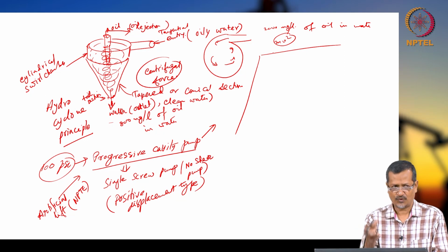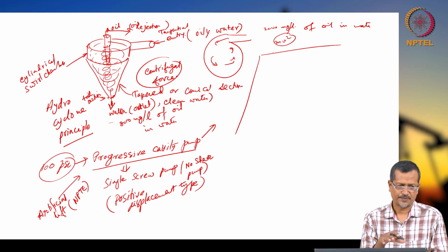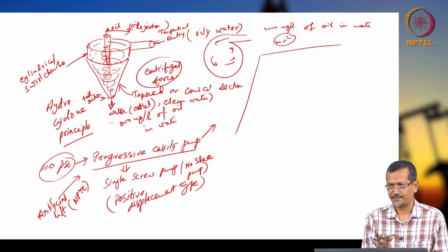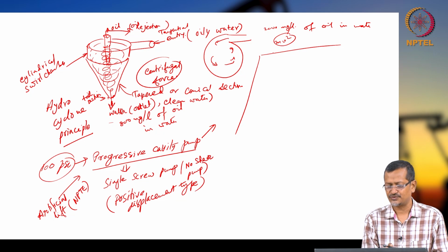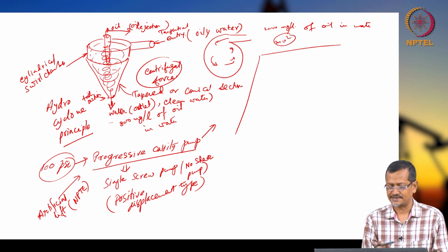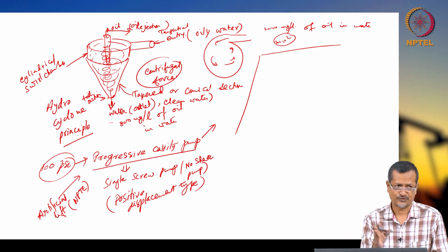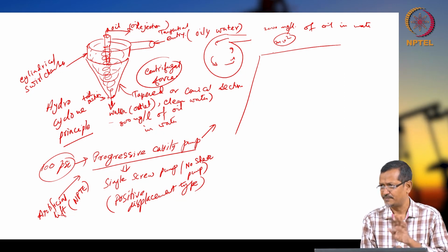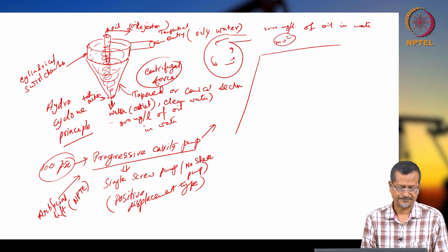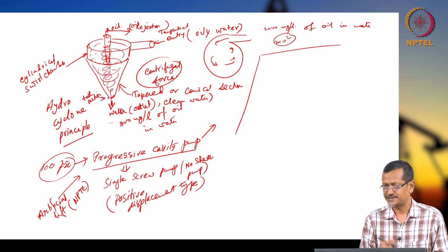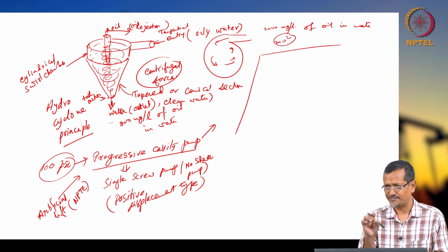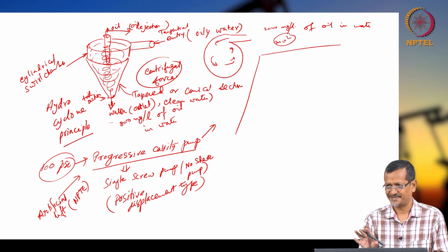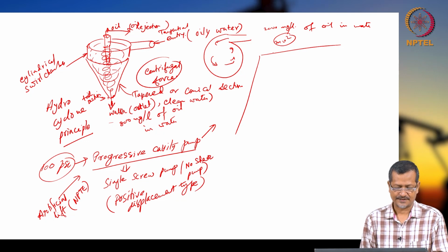If you have lower pressure than 100 psi, then most probably you will require one pump. Again, any pump you should not use, rather you should use a non-shearing pump. One example is progressive cavity pump or single screw pump. Multiple screw pumps they can also use, but they have given the example PCP, so just remember that. And the basic disadvantage is that if pressure is low, then you need extra energy to pump it.